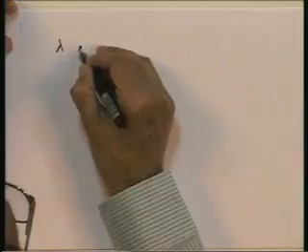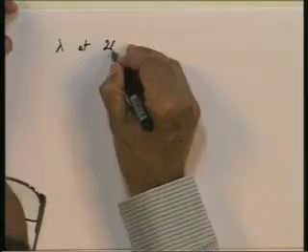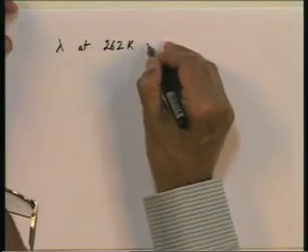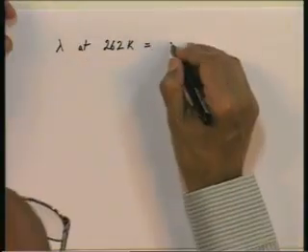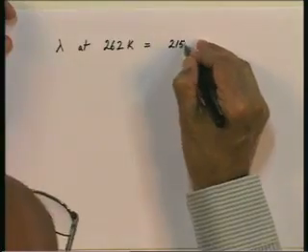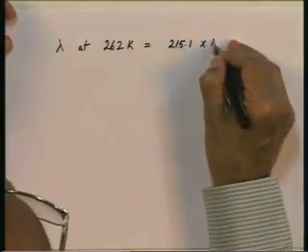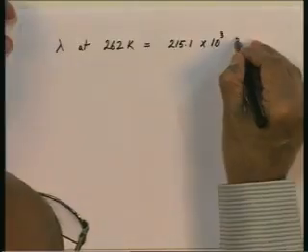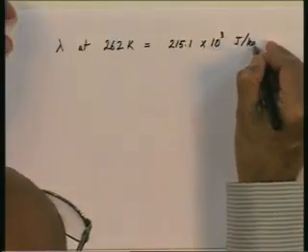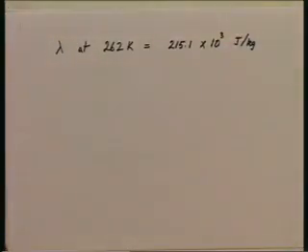In addition, we will need the latent heat, of course. From the tables, we need the latent heat at the saturation temperature, so at 262 K for R 22 vapor. If you look it up in the tables for R 22, it is 215.1 into 10 to the power of 3 joules per kilogram. So, these are the relevant properties that we need.